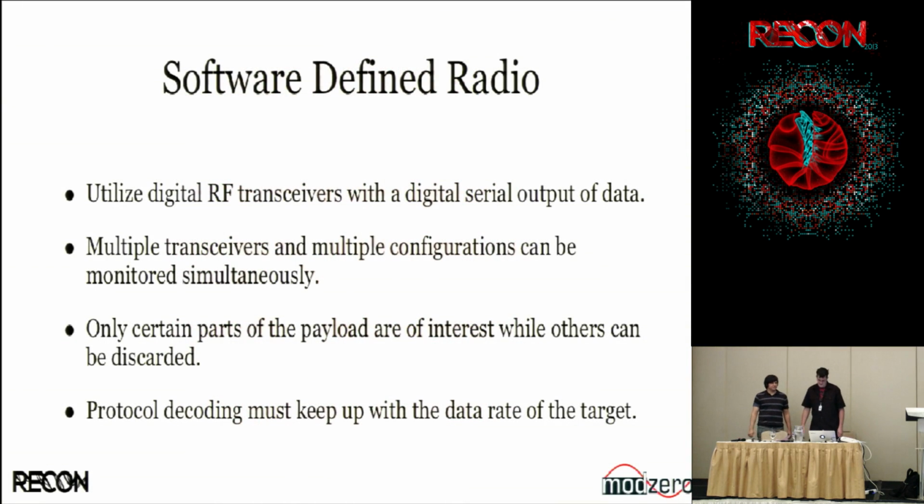Recovered. Yeah. So you can, if you're doing software-defined radio. One of my previous projects was to sniff wireless keyboards running with 2.4 gigahertz radio. The idea is just to add a couple of transceivers that are capable of providing a digital signal to the microcontroller, so zeros and ones, whatever gets transmitted over the air.